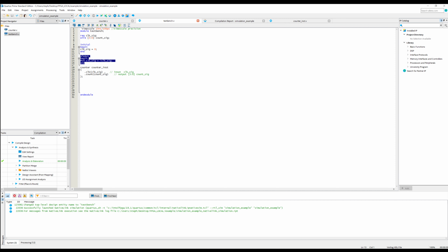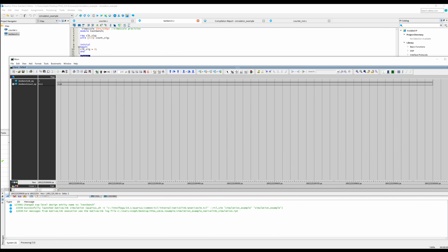If we went away and made a cup of tea, came back, it would still be simulating the same thing again and again. You only need a couple of cycles here to know what's going on for something as simple as this. So just to avoid it eating into the RAM of your computer, be ready to do Simulate, Break.